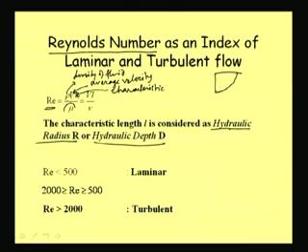And mu is the dynamic viscosity of the flow. Well, mu by rho is nu, which is the kinematic viscosity. So ultimately this Reynolds number can be expressed as VL by nu, and for pipe flow, as I have explained, this L can be diameter, and for open channel flow this can be hydraulic radius or hydraulic depth.